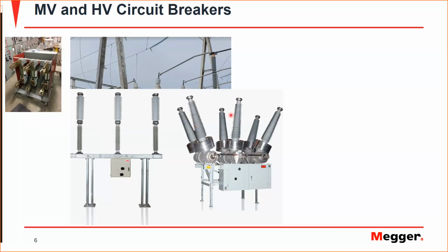As for the dead tank type circuit breaker, SF6 circuit breakers, not only for SF6, but sometimes you can also find it for other technologies. But the dead tank is usually something that allows you, for example, to do cleaning or a quick inspection very easily without any hazards, since the body of the breaker is grounded, hence the name dead tank circuit breakers.